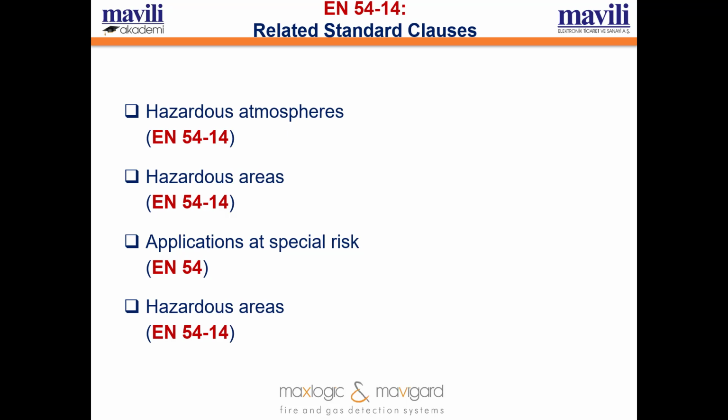Any special hazards that may exist in the location of the equipment must be considered. Note that, for locations with potentially explosive atmospheres, the requirements of the ATEX directive are taken into account. Special risks are those that require special attention and knowledge in design and selection of the equipment, the placement of detectors and between them, or the arrangement of circuits. These are electronic data processing areas, high bay warehouses, high ceiling areas, hazardous areas, and outdoor risks.